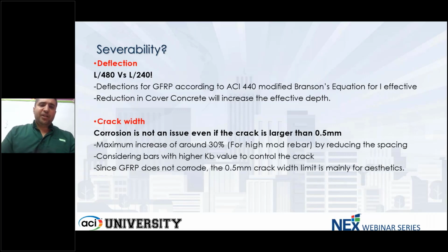Also, the other thing about deflection, when you look at deflection, the new code, the modified Branson equation that is in ACI 440, is actually a much better code to calculate your deflection. And again, going back to the discussion of why do you need to control the deflection? I had a great chat with a good friend of mine, Dr. Shamim Sheikh, regarding L/480. I was working with one of the consultant engineers on a parking garage, and they were designing this parking garage on L/480. And I said, hey, I don't know if you need L/480. You might be able to use L/360.